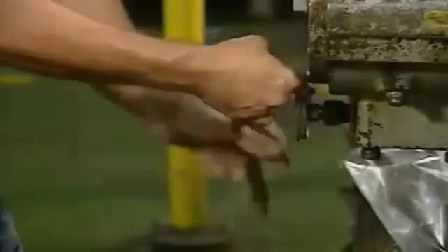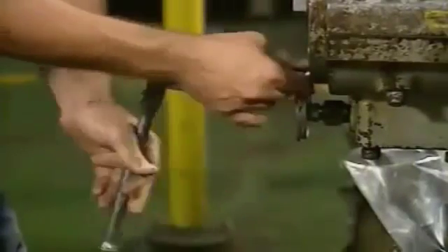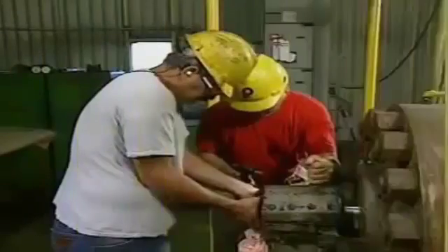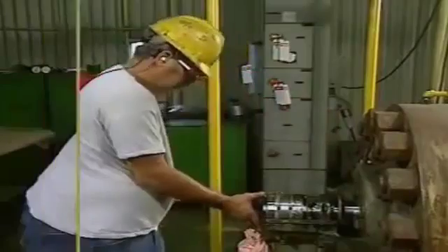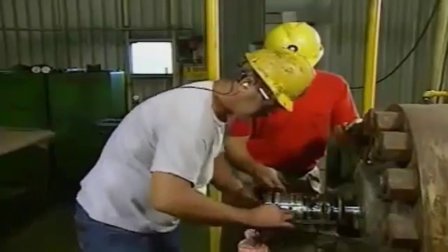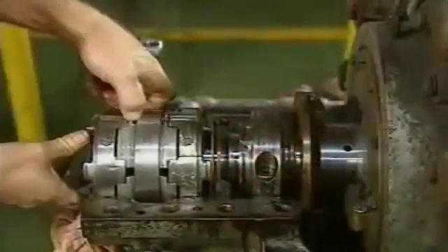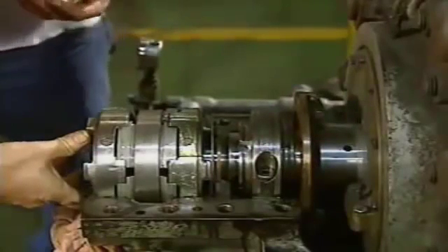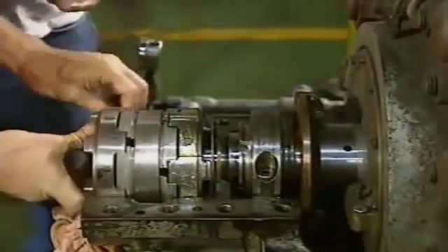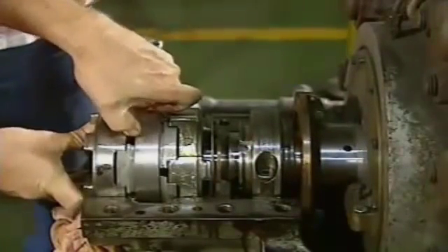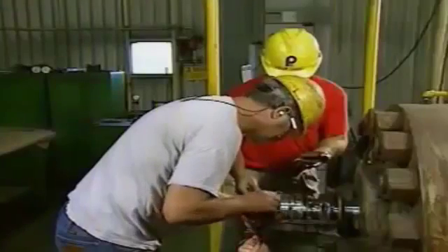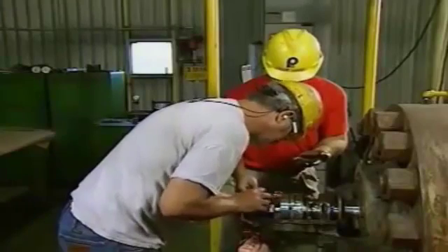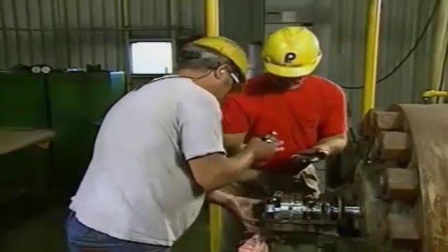The mechanic removes the end plate and the housing bolts and guide pins. He then removes the top half of the bearing housing. The outboard thrust bearing is removed first. The mechanic begins by removing the thrust shoes. The thrust shoes are placed on a clean work surface to prevent them from collecting dirt. Then the support brackets are removed. They are also placed on a clean work surface.